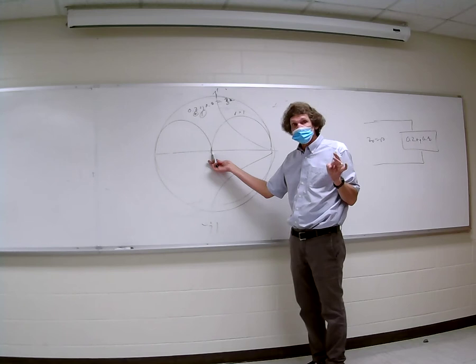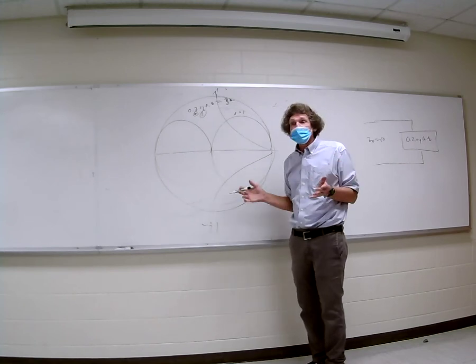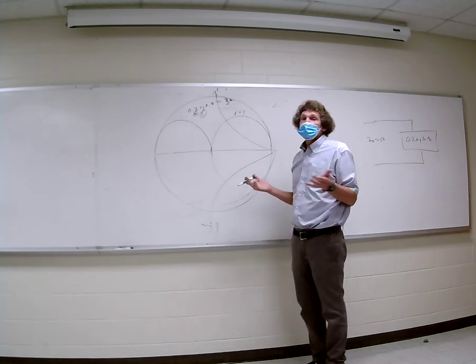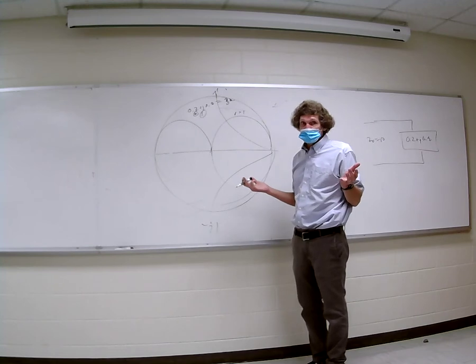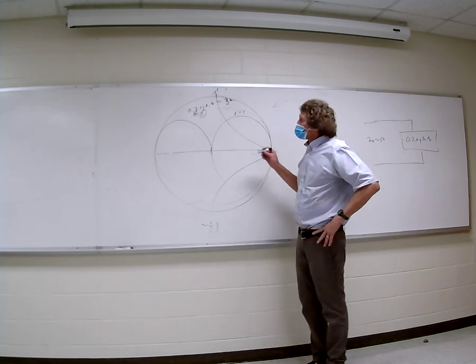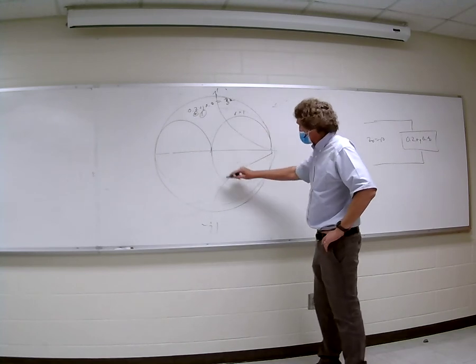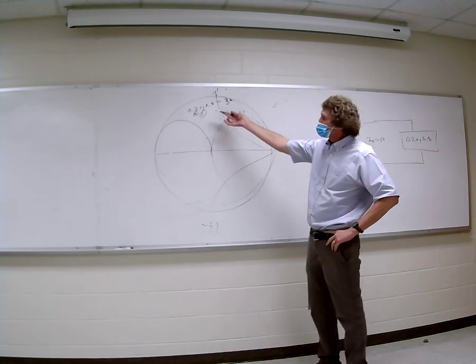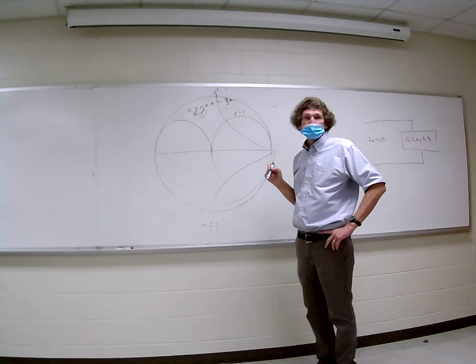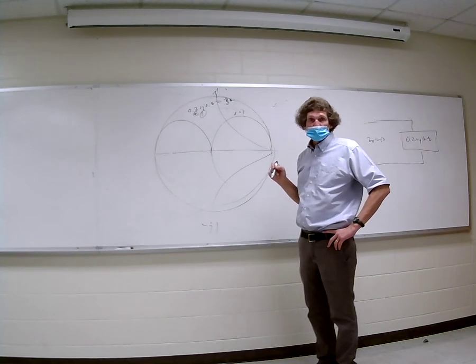That's the center of the circle. Doesn't matter if it's an admittance or an impedance. They're the same when they're normalized at the center. You all see that? All right. So no matter what we add in series, we cannot get to this one circle. Just can't. Because we're always going to have 0.2 for the real part. Y'all with me? We want a real part of 0.1.